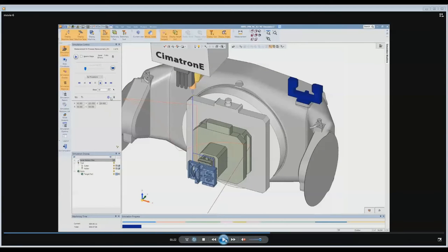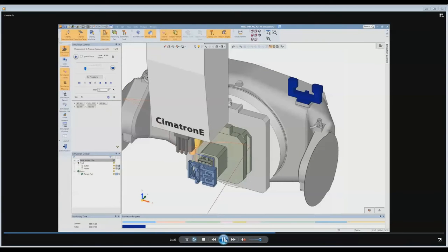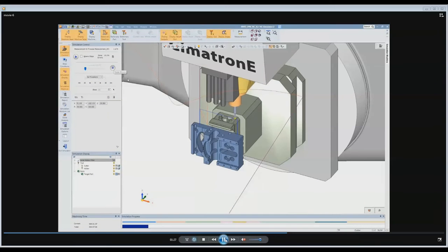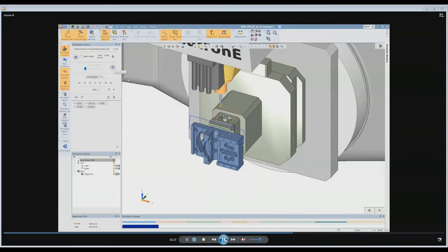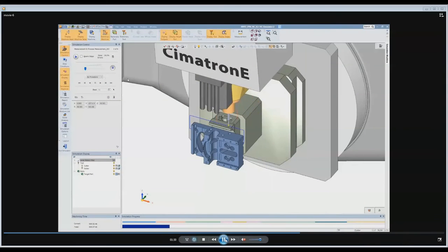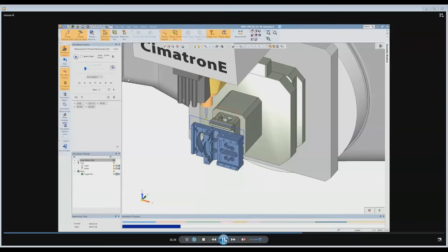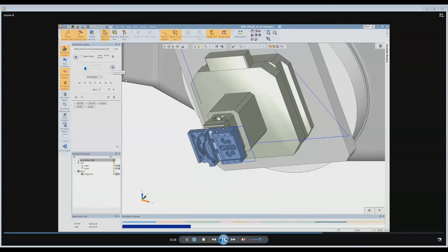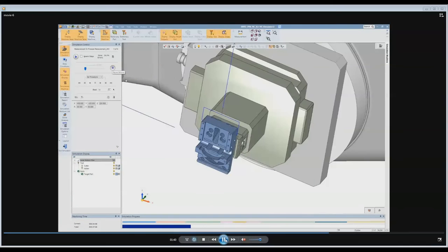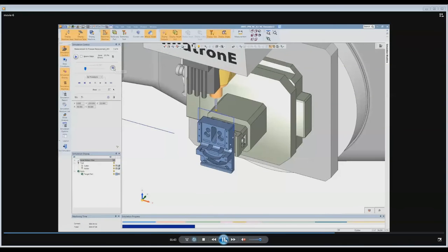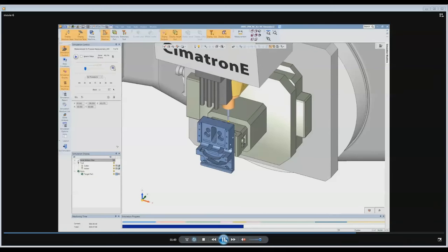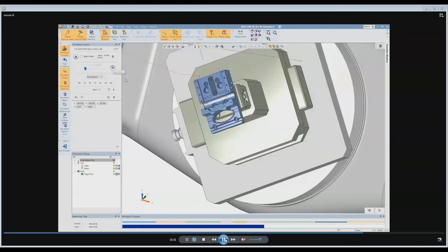Now we are seeing the complete simulation from start to end. And this is the C-axis alignment, X center, rotation of the job for Y centering. So we are seeing the simulation of the probe. And now actual milling will start.